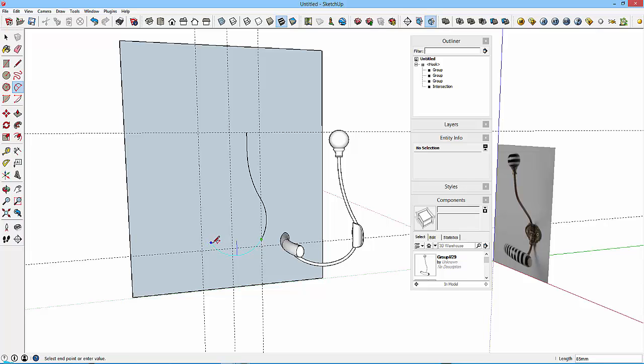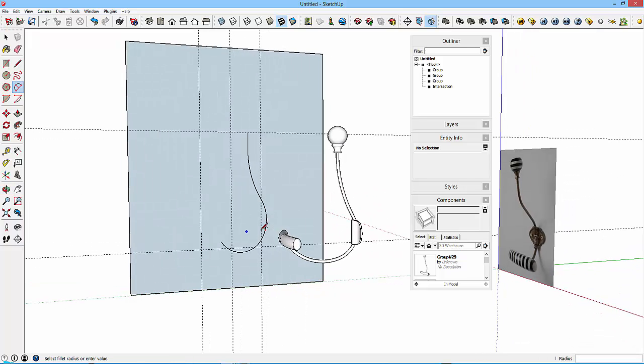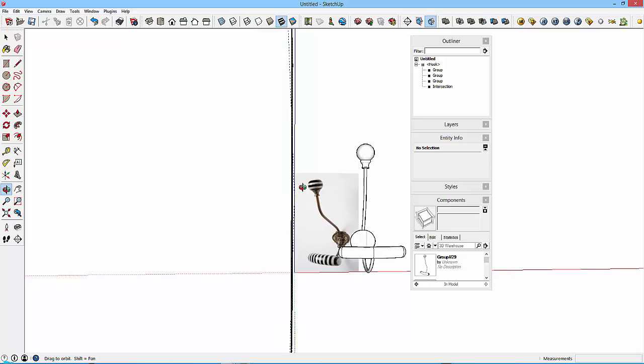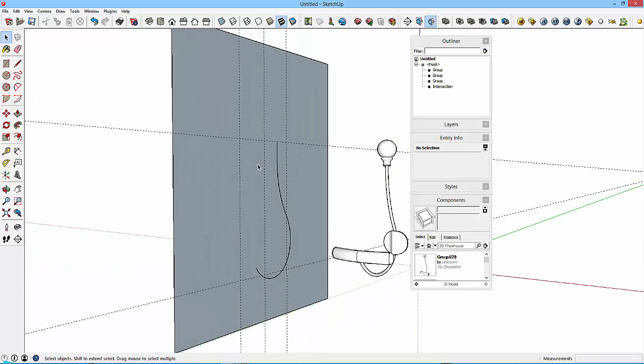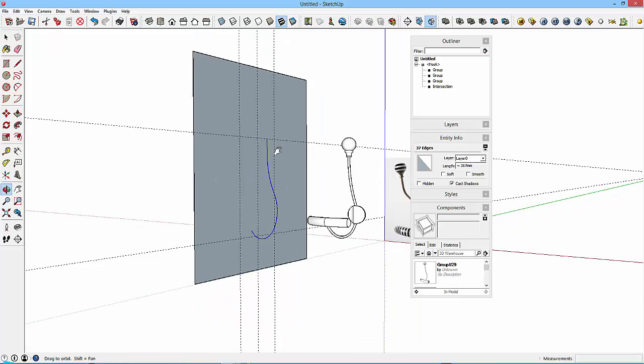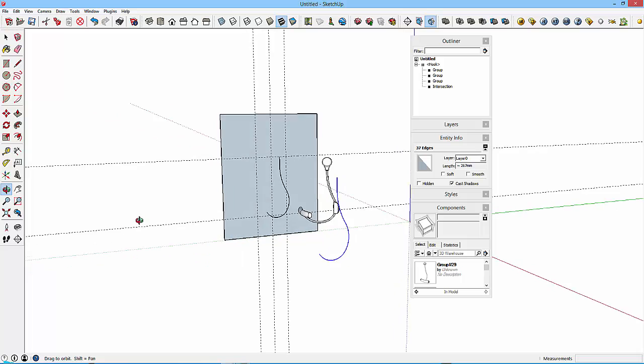It's slightly a bit too level, come in a bit and come down. So that's that hook shape. It's probably a bit more like it. It is a bit more angular than I've drawn it, but it really doesn't matter. Okay, so that's drawn on that surface. Make sure it's flat, so it is, and then we can select this and copy it a known distance in a known direction. So in the red axis, I'll go 500. So I can just move it well away from that.